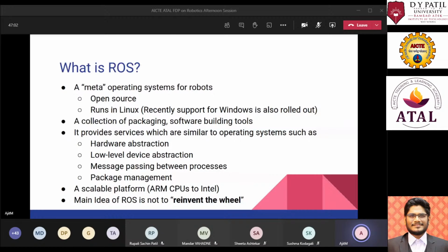You can see what is getting published on that topic, and who is getting subscribed to that topic. You can also get information about that topic, like what message format is being used, what is the frequency of that topic, all these things. So ROS master, then ROS publisher, and ROS node. Once you get registered on the ROS master, ROS node 1 can publish messages on ROS master, and node 2 can subscribe to those messages using these ROS topics.